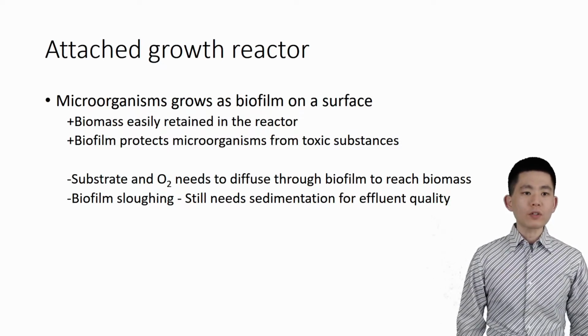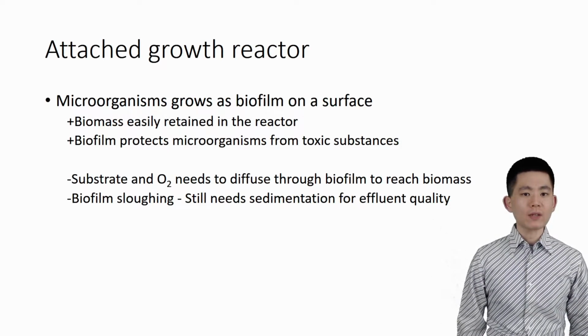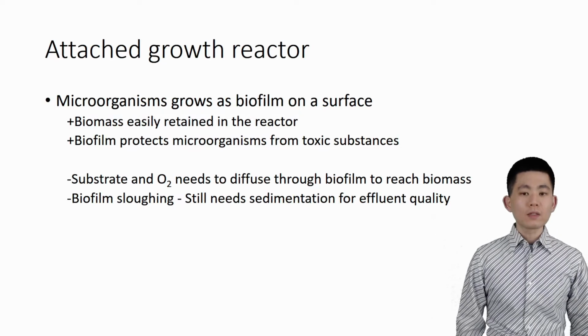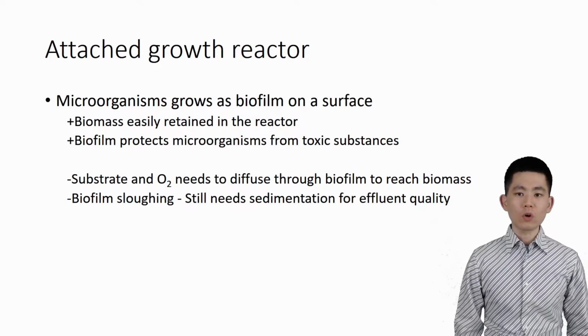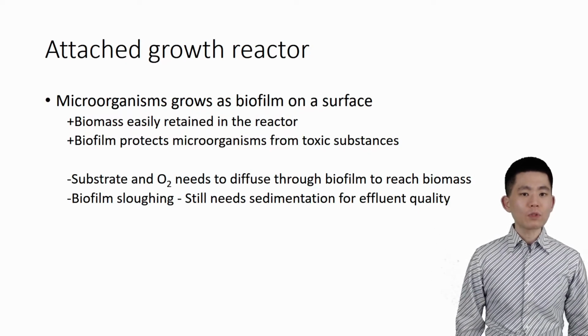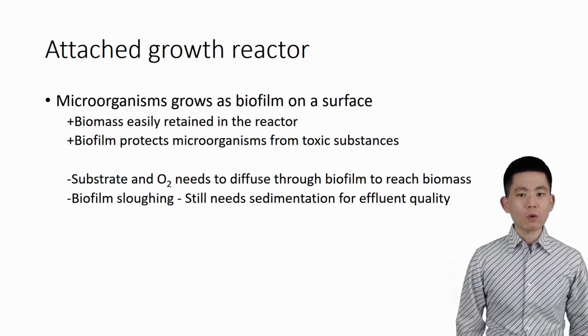But the biofilm also forms a barrier between the biomass and substrate. Substrates and oxygen need to diffuse through the biofilm to reach the biomass and to be utilized. Moreover, biomass sloughed or shed from the biofilm needs to be removed or it will impact the effluent quality.